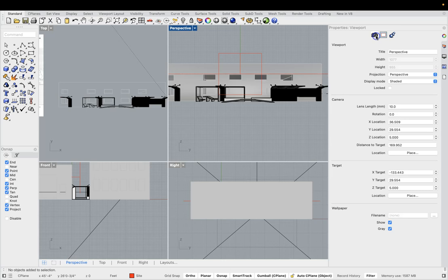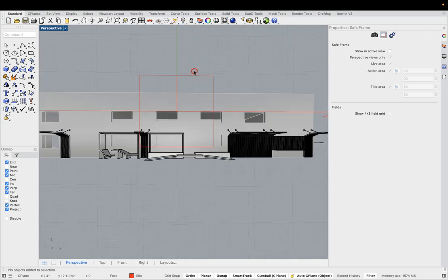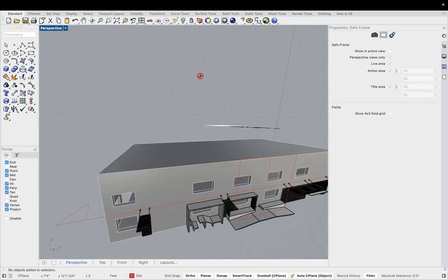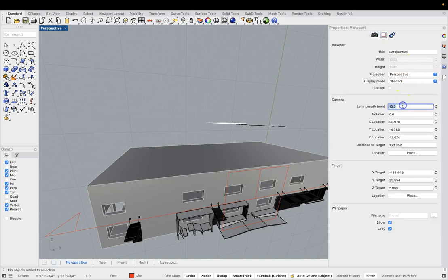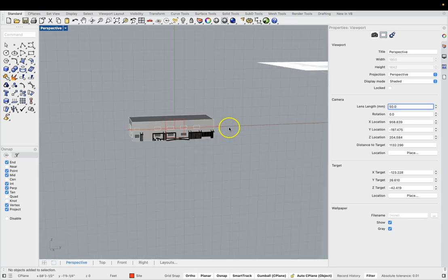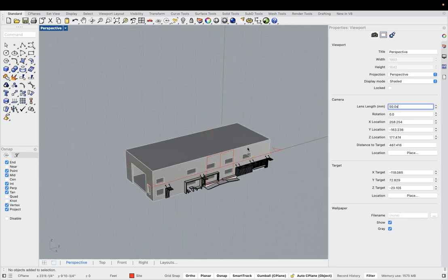So we can come here and begin to save a view, but also, just so you can understand this, right, as I come out here, you can see how distorted the image is, right? So I want to make sure to come back to my properties and change this back to 50 whenever I go back to model, right? So that's the beauty of the name view, would allow me to come back, okay? But I also, I'm going to show this clipping plane again.